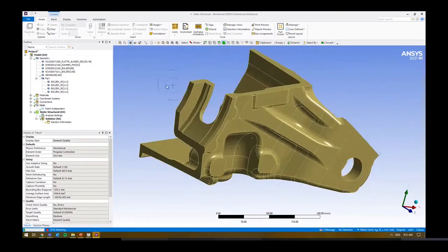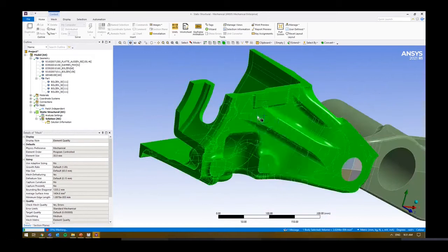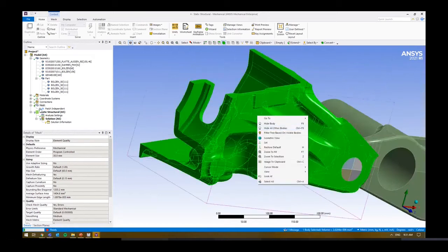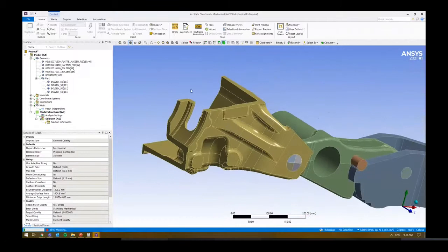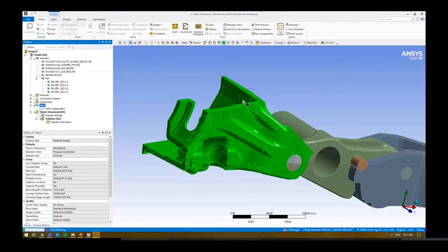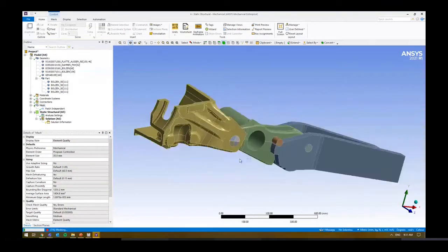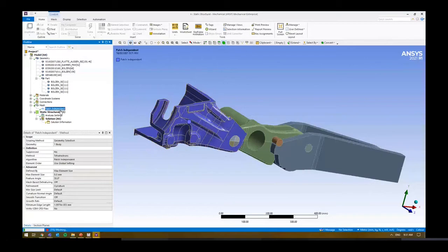The other thing that I've been doing, by the way, is what's called selective meshing. I can select a specific component when it's not meshing, and I can generate on that specific component. We can move around to other components as well. And this is generally how I'd start with something. Maybe tune in the global settings to make sure it captures the broad features that you're after, and then focus on specific components using your local sizings as well.